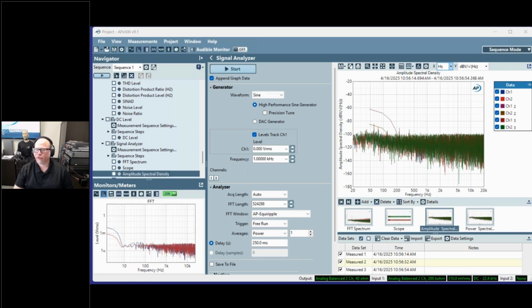So the difference between dBrA and dBrG. dBrA is an arbitrary reference value for the input. If you want to express measurement results relative to some value, you would set dBrA, or there is a second one, dBrB, to the value you want to be referred to. dBrG is a generator reference value. If you want to set the generator amplitude relative to some reference value, you would use dBrG for that.